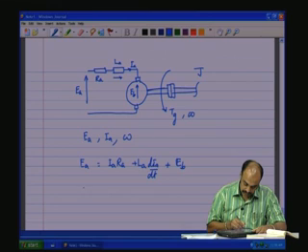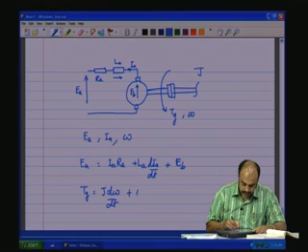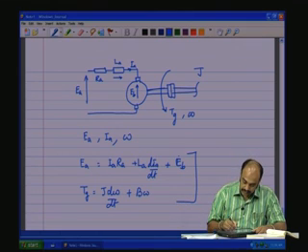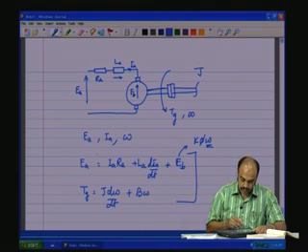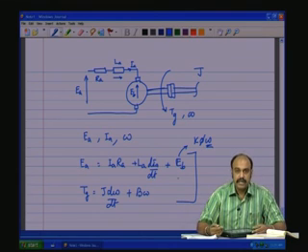The other equation is TG equal to J d omega by dt plus friction into omega, same as in the case of the DC generator, and this will be K into phi into IA. So, this is also expressible in terms of state variables and input variables. Use these two equations to obtain the state equations.